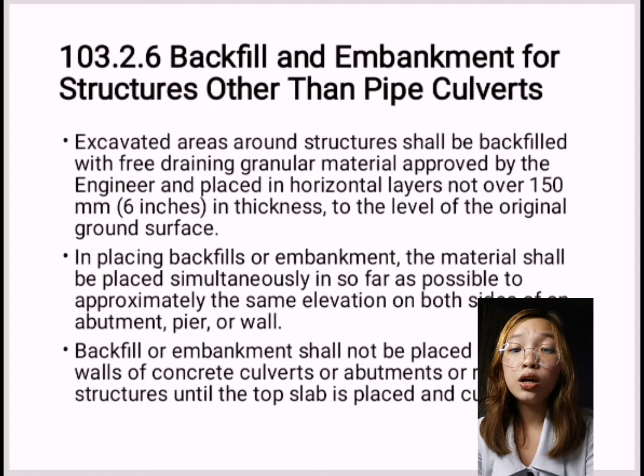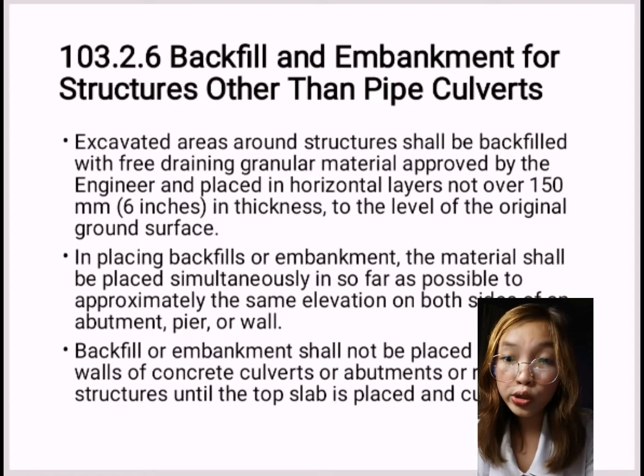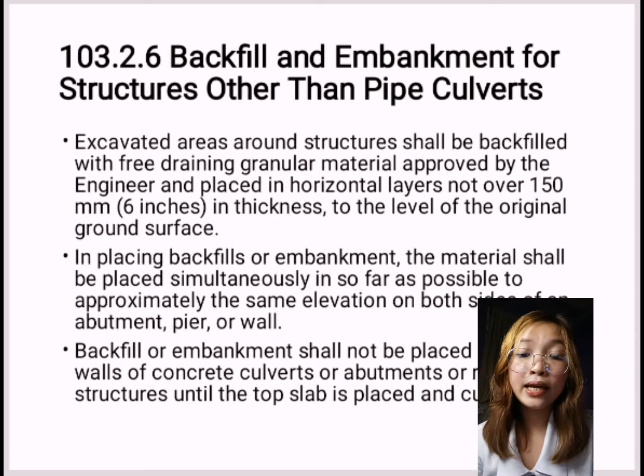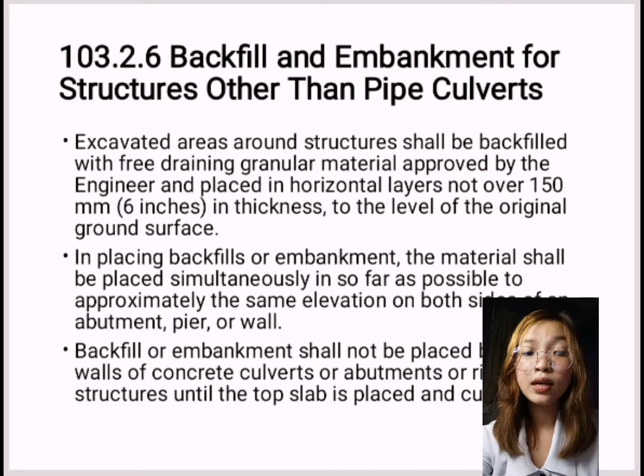Each layer shall be moistened or dried as required and thoroughly compacted with mechanical tampers.